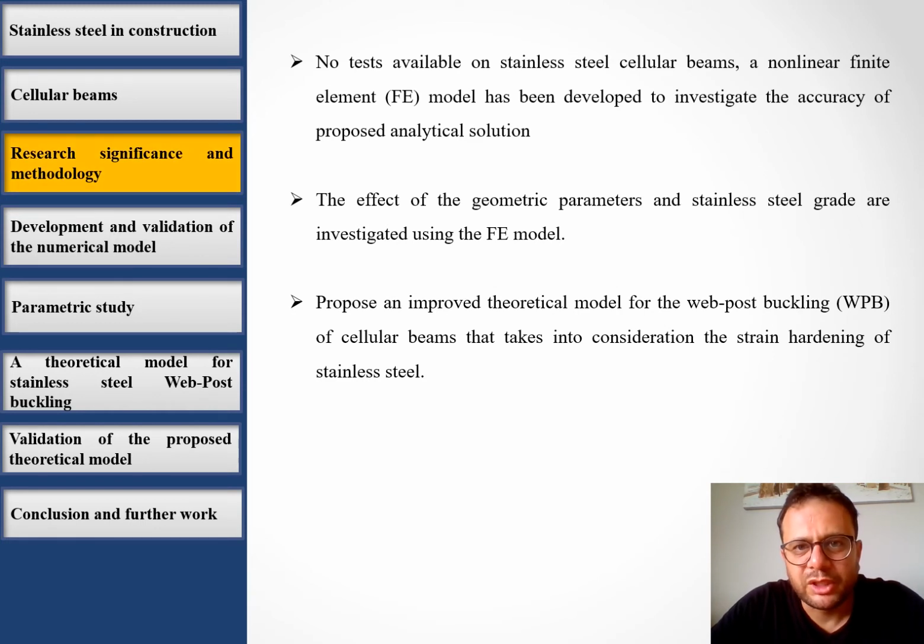In our methodology, we will use nonlinear finite element analysis, because there is no experimental testing of cellular beams made of stainless steel. The effect of geometric parameters and stainless steel grade will be investigated numerically. Finally, we will propose a theoretical model for web post buckling of cellular beams made of stainless steel, which will take into consideration the material hardening of stainless steel.